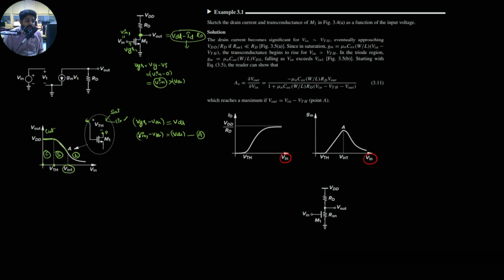As you increase the V input, and then still increase it, it comes from cutoff, goes into saturation, then goes to the linear region. So you cannot give excess input voltage and you cannot give low input voltage. If you give low voltage, it will be in cutoff. If you give excess voltage, it will go into the linear region. So you have to give a sufficient DC biasing voltage, upon which you do the variations of the input.